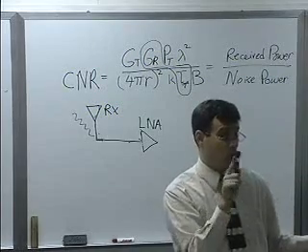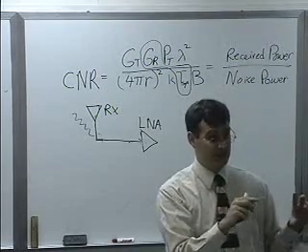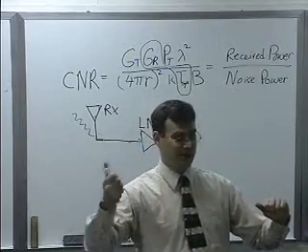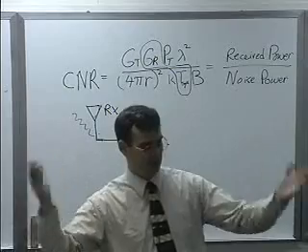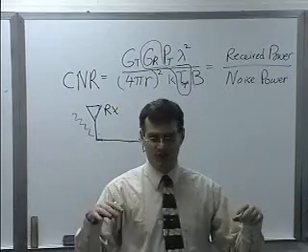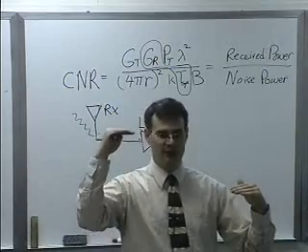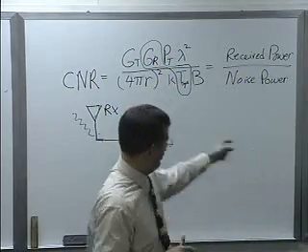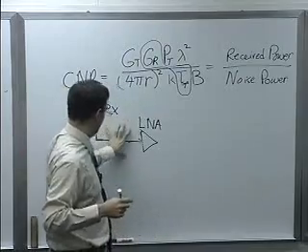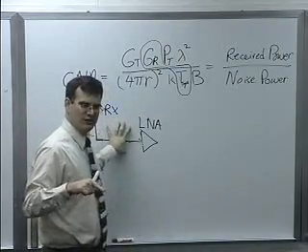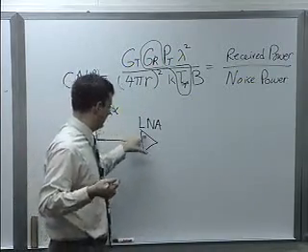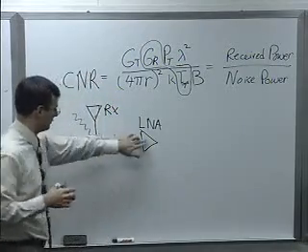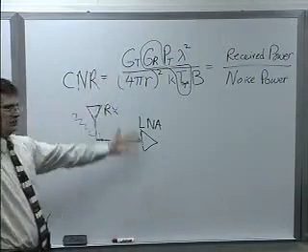So the worst that they'll probably influence the system is in-band interference. Like they'll shoot a harmonic up into 30 gig, and maybe you've got some sort of satellite link that works at 30 gig. And then that'll be part of your signal-to-noise ratio. You've got to step up that noise power for that. The harmonics generally are less of a concern for this front-end filter that would go in front of your LNA, because they're generally not strong enough to force this nonlinear. That's really the only thing that this filter is trying to do: keep this from going nonlinear with all the other stuff that's out there.